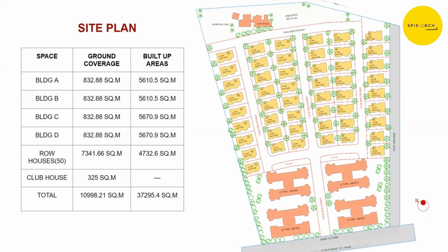Normally, where are you supposed to provide the community space, if you are designing any cluster? At the center. At the center or at the beginning? Why at the beginning? It all depends on the location of that particular site. Because that is a mandatory open space, and that is required for the people who live in it. It is for their convenience, it is for their benefit. When you are designing 2-3 clusters, then each and every cluster should get the benefit of the open space where the kids play. The landlady doesn't send her kids to an open space which is far away from the apartment or flat in which she is residing. So you will have to take this point into consideration when you design your project.